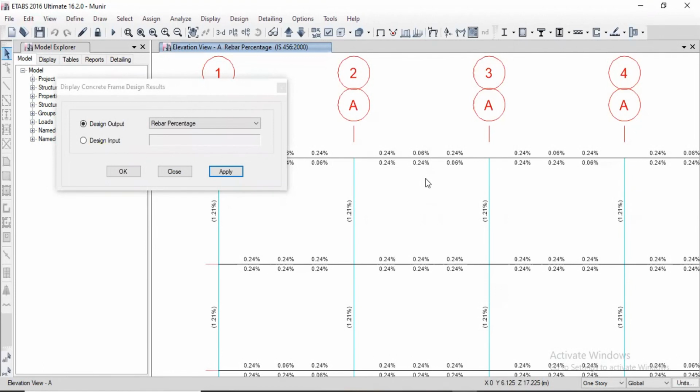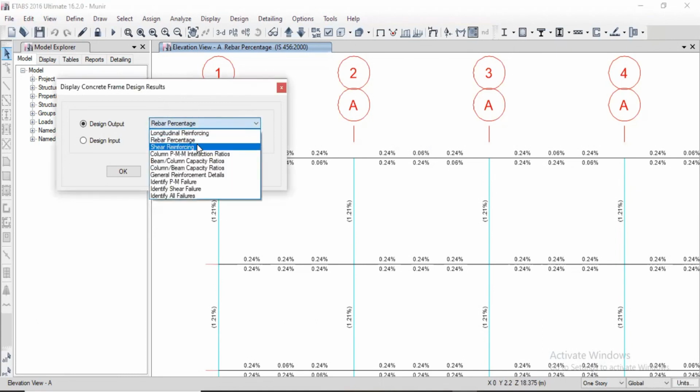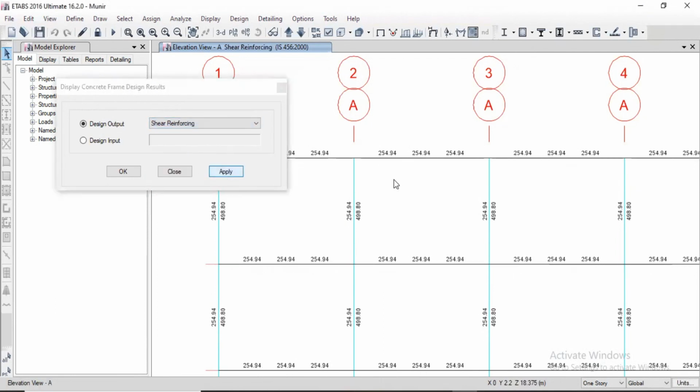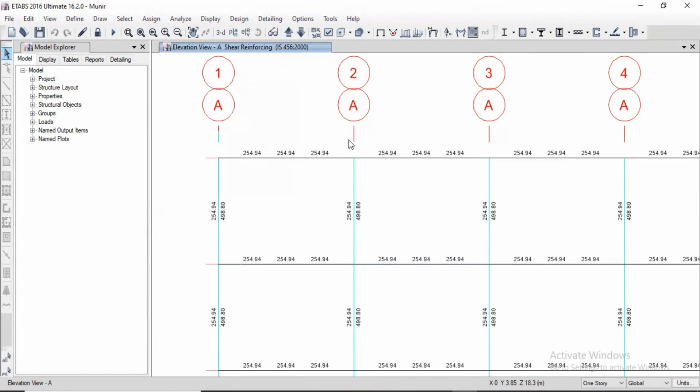But here do we exceed 2%, 0.24? It is not exceeding 2%. This is 0.24%, which is less than 2%. Yes or no? Okay. Now the next one is the shear reinforcement steel, the stirrups, which I have shown in the tables. That is the major reinforcement and minor reinforcement. Understood? So you understand how we have to check the result.